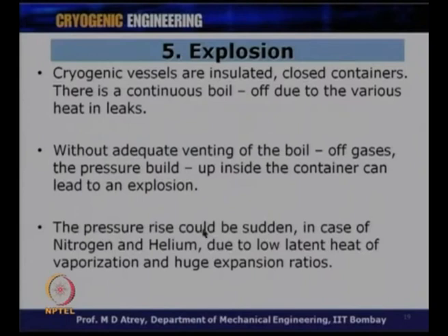The pressure rise could be sudden in the case of nitrogen and helium due to low latent heat of vaporization. That means, as soon as some heat inleak happens, your helium and nitrogen especially can suddenly get boiled off and sudden pressure can get built up. They also have a huge expansion ratio, 1 to 1000, 1 to 800, that kind of ratios we are talking about, when 1 liter of liquid nitrogen becomes almost 800 liters of gas at room temperature. Therefore, this pressure rise could be sudden, and this is a very important aspect that has to be dealt with.